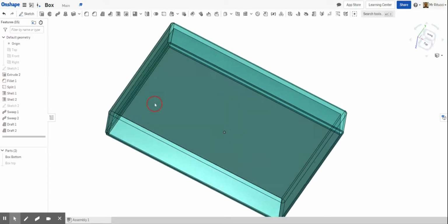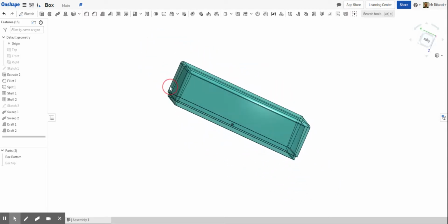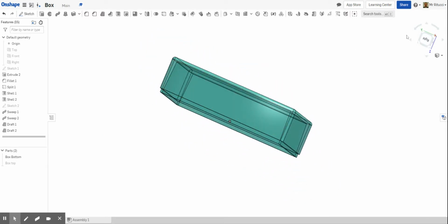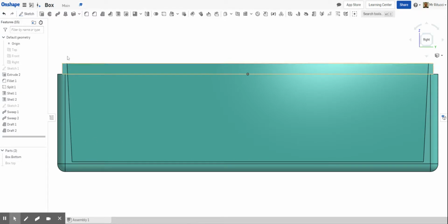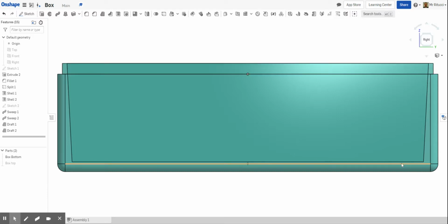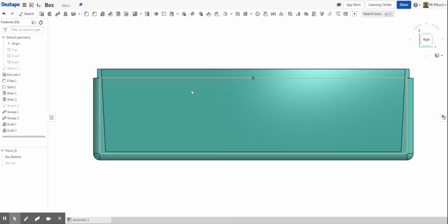So to create those lips for two boxes to slot inside each other, we've also got, if we look at the right view, from the internal part, this draft angle here. So the box goes inwards. Again, we've learnt about angles when we learned about vacuum forming. This is in place so this could come out of the mould if this was a manufactured part.